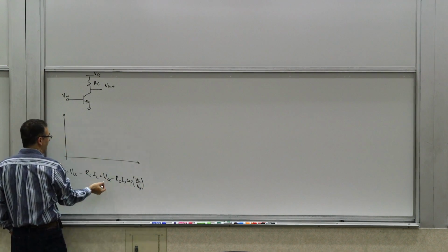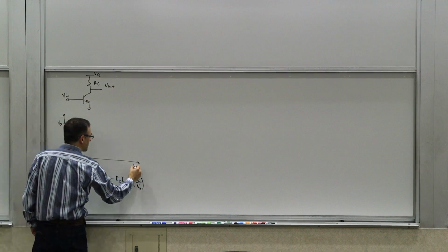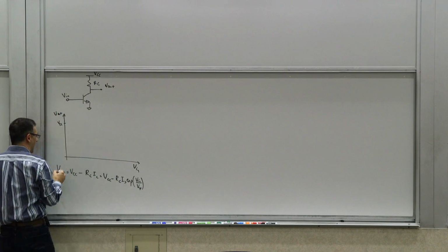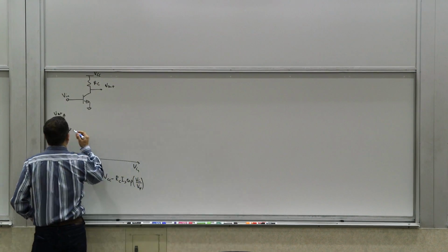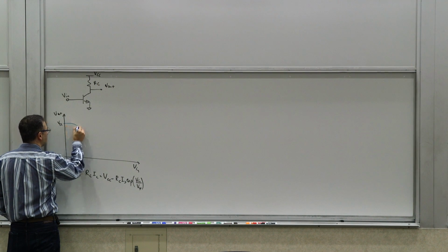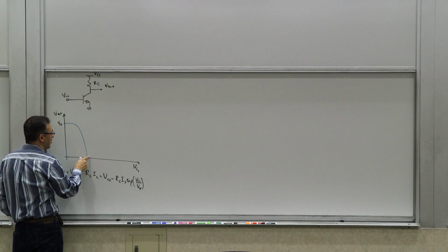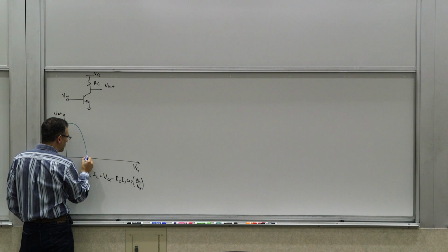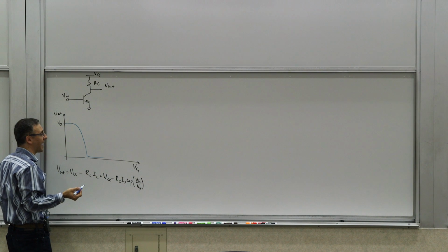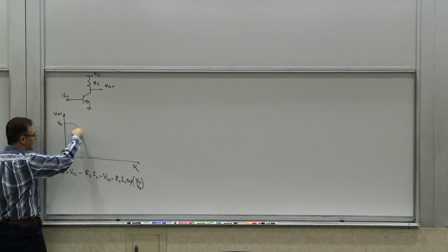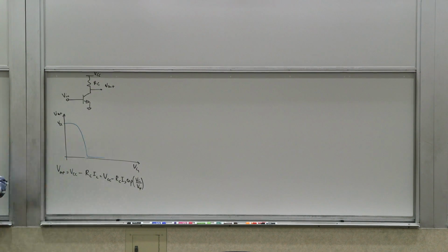And if you plot that, of course, that's for forward active region. So you start from VCC when the Vin is 0. So this is Vin, this is Vout. And you initially start turning the transistor on. The current is small first, but then it grows exponentially. And then, of course, it's not going to go negative, because once this voltage gets below a certain level, which is like 0.1, 0.2, this transistor is going to enter saturation, meaning that the base collector junction is going to get forward bias, and you get something like that. So that would be the characteristic. And of course, the gain is the slope of this thing, which you can see is negative, and depends on where you are. You can see this is a very nonlinear behavior, of course.